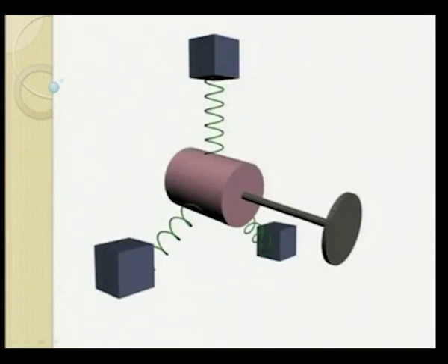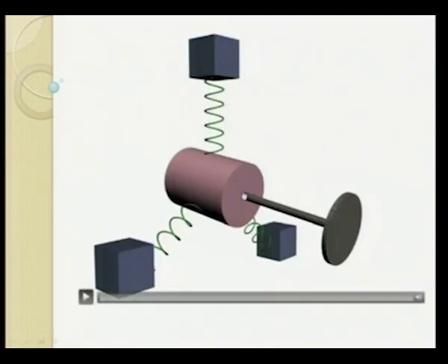This is the animation for the motor and the shaft whirling. This particular motor is whirling because it is mounted on a spring which is providing torsional stiffness, and the spinning is very fast. So here we will see the whirling and the spinning frequencies are different.